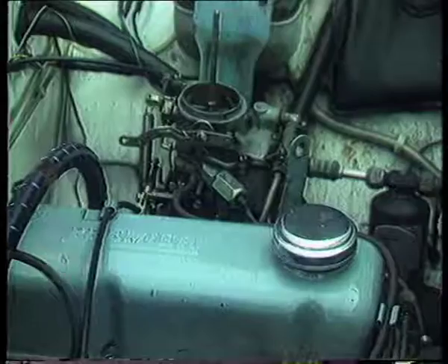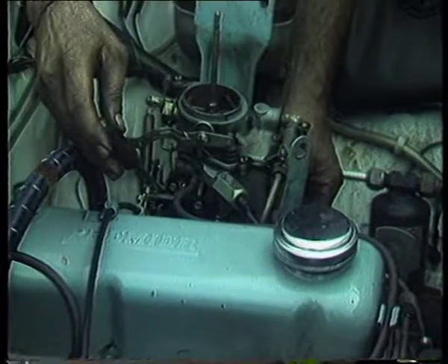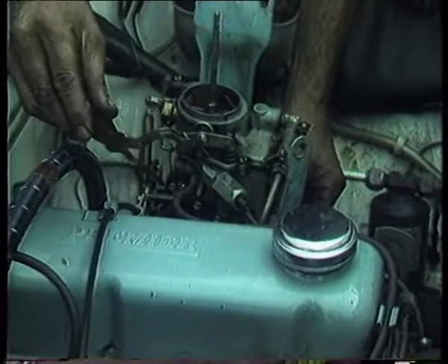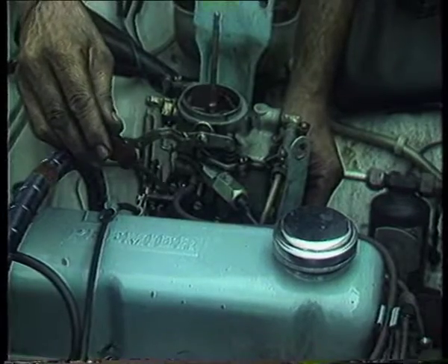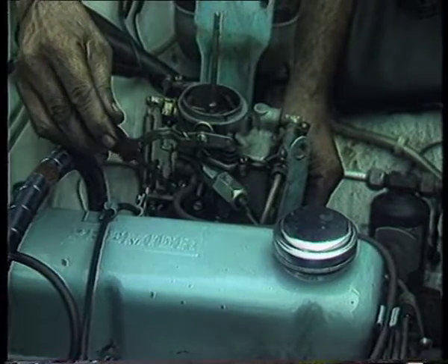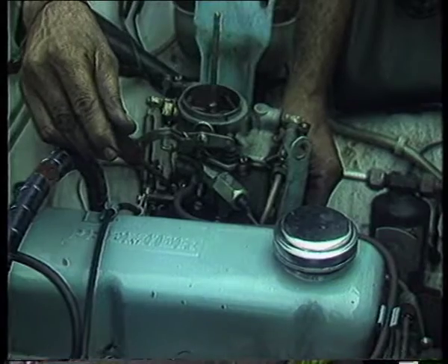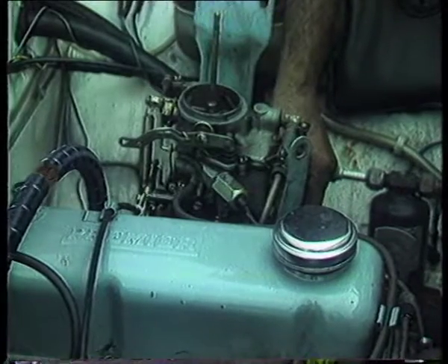Here the fault could be either with the idling adjustment, or there may be some dirt caught in the slow running or idling jet. It should be adjusted at the normal working temperature by turning the idling screw so that the engine does not run heavily or vibrate or stop after moving some distance.